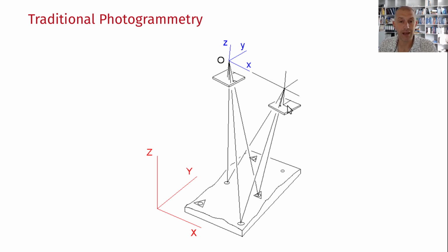Using this, you can make many assumptions, and you can use collinear and parallax approaches to determine points on the surface. You're essentially generating triangles between one camera and the second camera, and a key point identified on the surface. And because you're looking at it from two different directions, you can measure the height offset between those different views. I'm not going into further detail here, but traditional photogrammetry is not what you do with structure from motion.